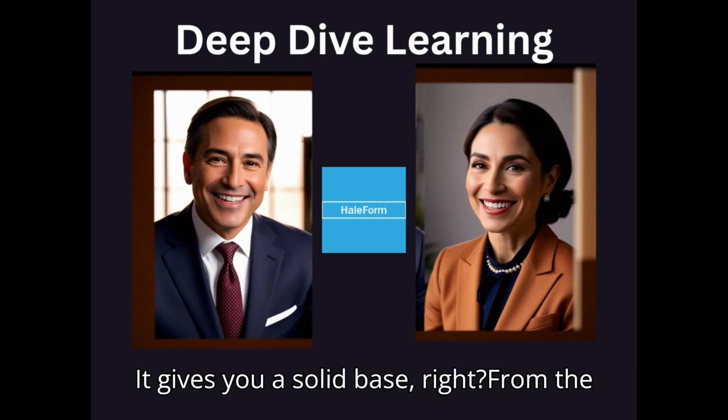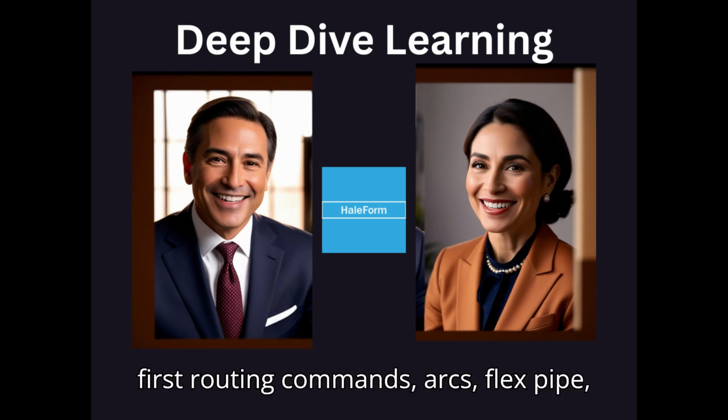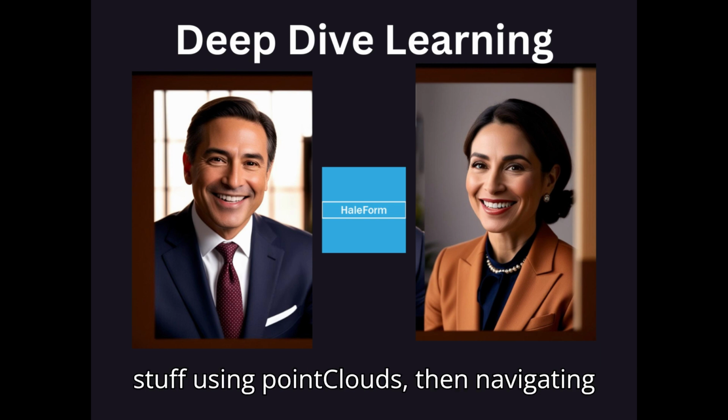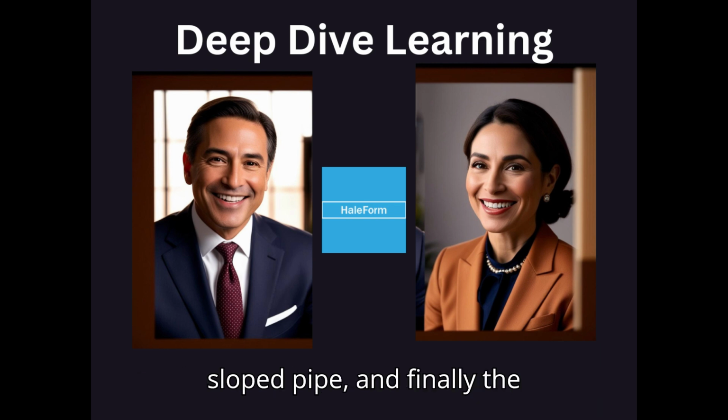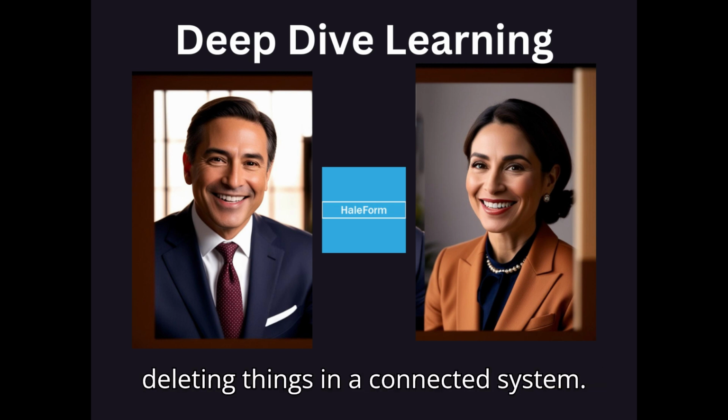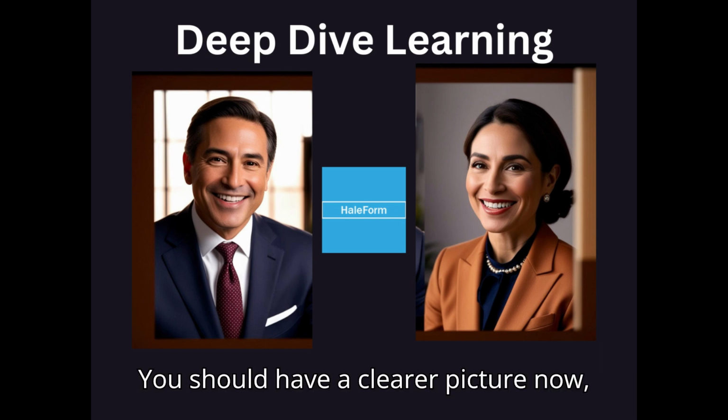It gives you a solid base, right? Yeah. From the first routing commands, arcs, flex pipe, all that, through the precise coordinate stuff using point clouds, then navigating sloped pipe, and finally, the sometimes tricky business of moving and deleting things in a connected system. You should have a clearer picture now.